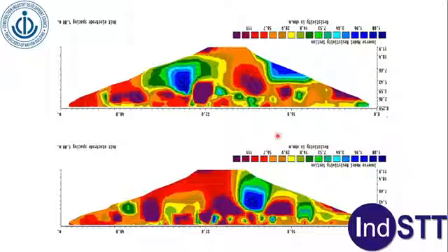The next method I will quickly cover is seismic tomography. Seismic tomography becomes very important because sometimes you are working in an area where, for example, your bore path is going under buildings. You do not have any access there, you cannot do any drilling, but if you can do two holes on either side, anything can be on top here. It can be a house, it can be a building. If you can do two holes on either side, everything in between can be mapped using seismic tomography.